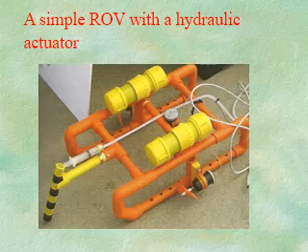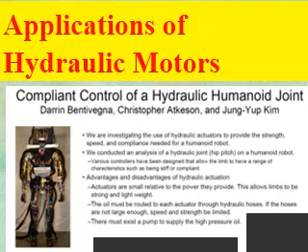Actually, the pneumatic air is received from the atmosphere. The received air is increased in pressure from a lower level to a higher level, above the atmospheric air. Then this air enters the direction control valve or check valve. Based on the check valve and direction control valve, the pneumatic air flows as per our requirement, as per our applications.